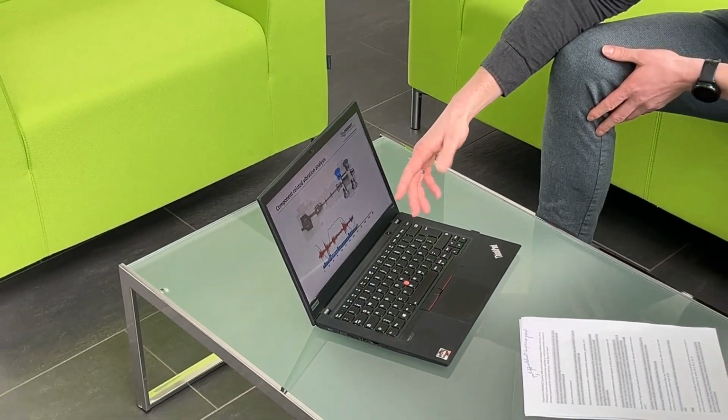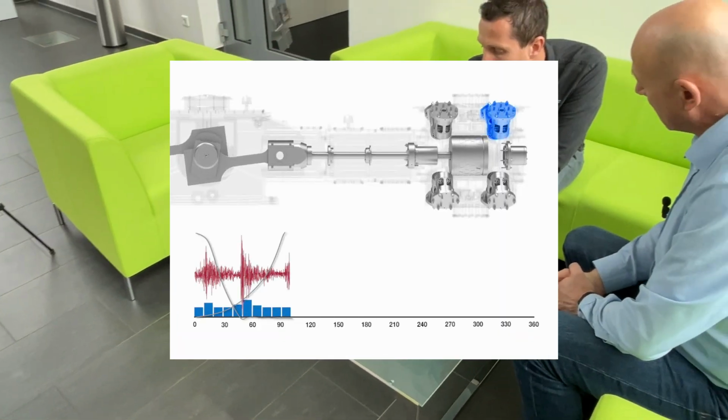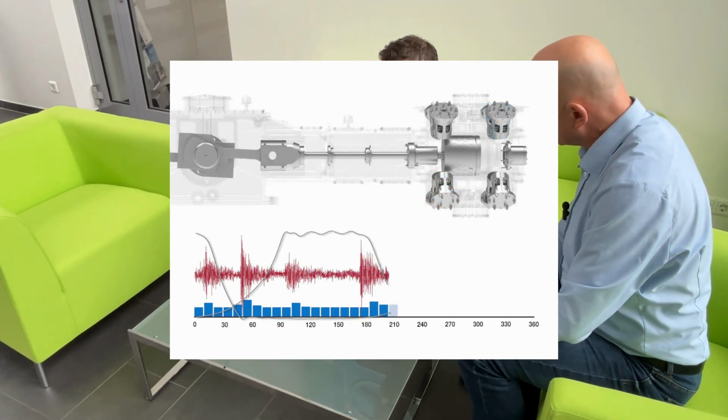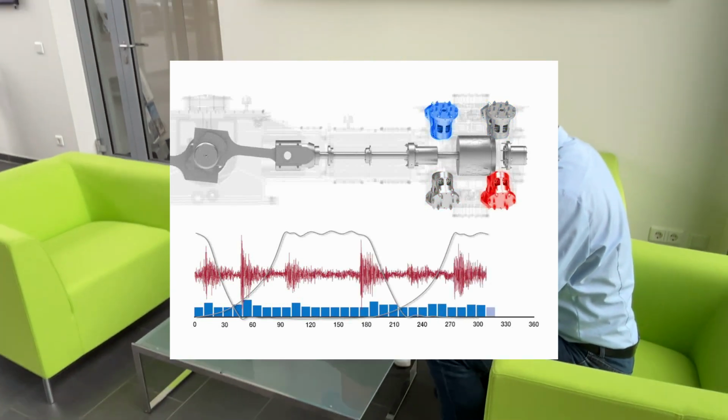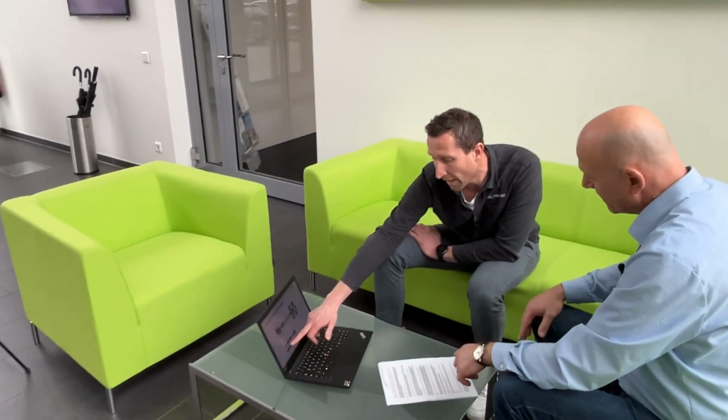The reason is that you can see here, there are some areas, some segments that have higher vibration in the signal. And that's normal because of the valves opening and closing in the compressor. You have some vibration in the compressor. That's normal. That's like the footprint of a compressor, and that's what you want to analyze and see.